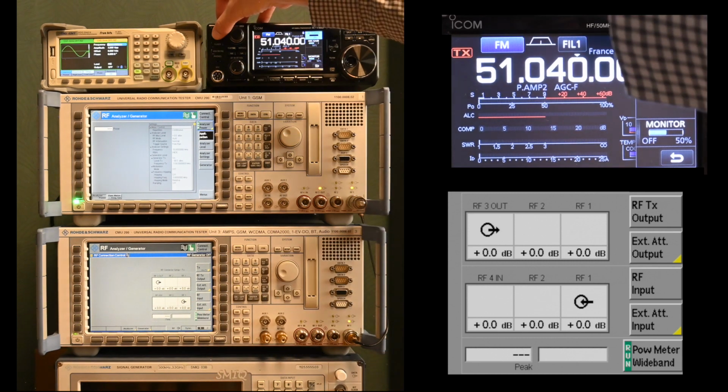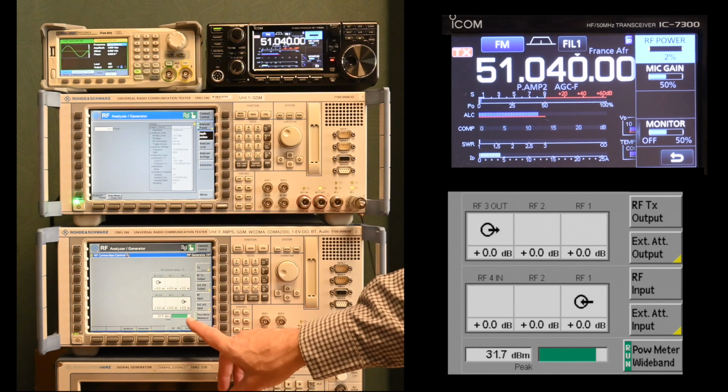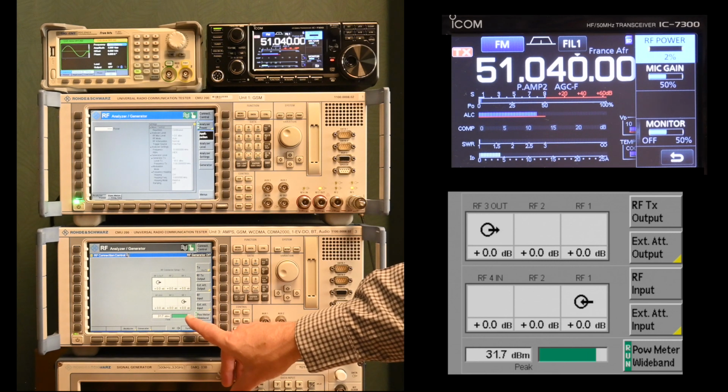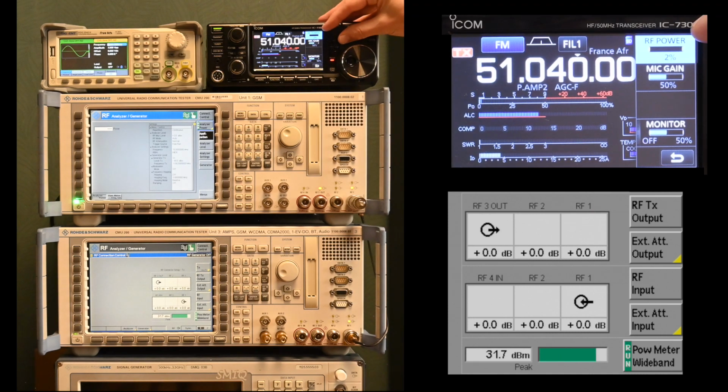So again, let's turn on the transmitter. And we're getting to see, yeah, again, 31 dB. So this is what we also expected. That's what we saw on the other unit as well. But of course, here we're already at the upper bound of its measurement range, because this is the 2 watt unit. And we can already see that here graphically in this indicator. So we might be able to go a little bit up here and overload the unit slightly.